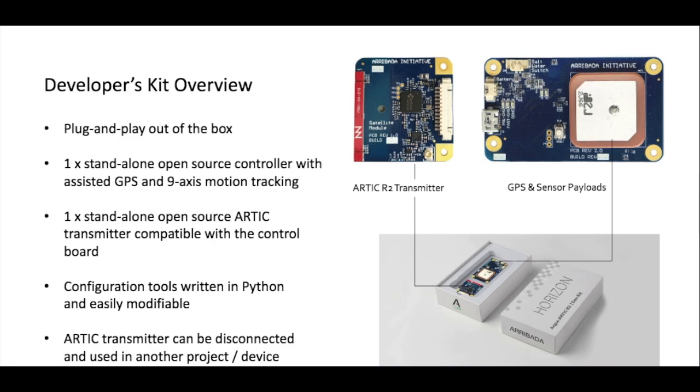So again, it's a standalone open source controller fitted with GPS, I2C, so you can break out into various sensors. We break out SPI and UART, all that connectivity is there. We also pack it with a good 9-axis accelerometer. And also, the reason we made this as two standalone units is because we want you to experiment and play with the satellite unit, but not have to go away and respin your own boards and pay those upfront costs to progress and move forwards.